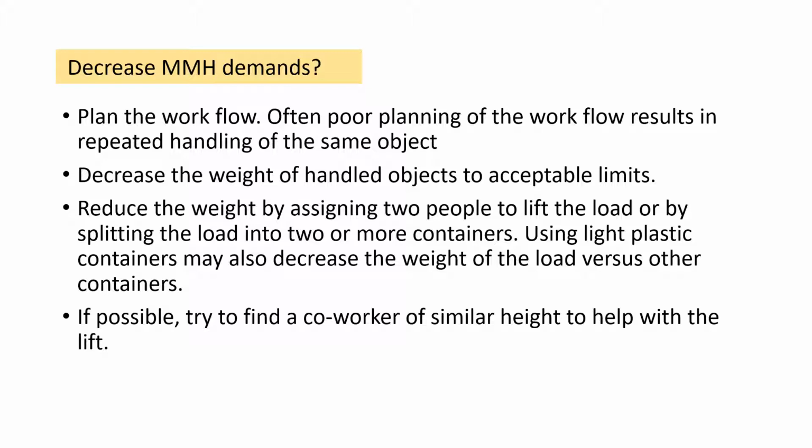It's important that you respect the acceptable limits for MMH, and you can also reduce the weight by assigning more people to lift the load, splitting the load into different containers, and even using less heavy containers to reduce the load.